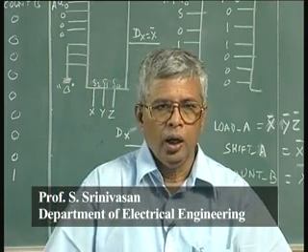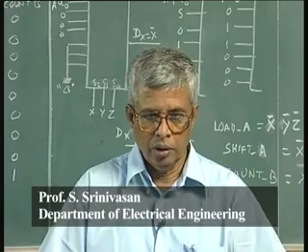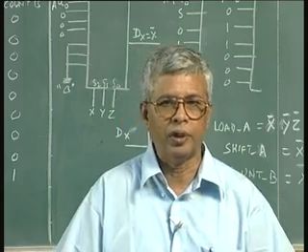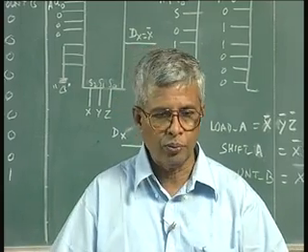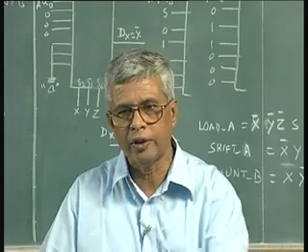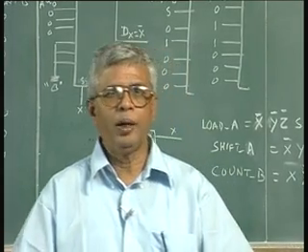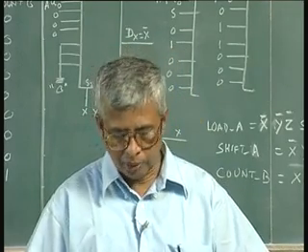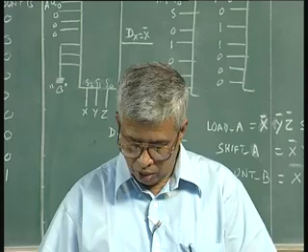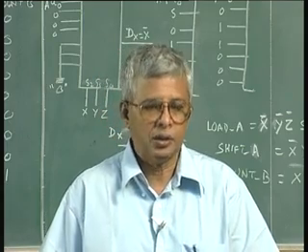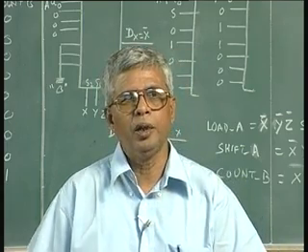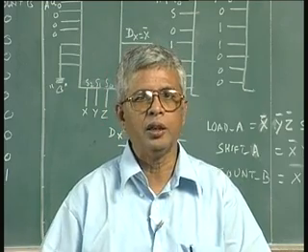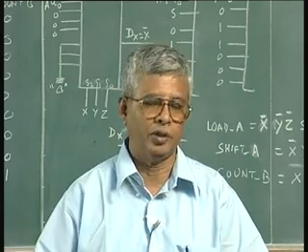And then we talked about how, instead of going through gate solutions or simple building block solutions, we can go to higher levels of integration. We talked about integrated circuit evolution from small scale integrated circuits to medium scale, to large scale, to very large scale integrated circuits. So, we talked about SSI, MSI and LSI components for combinational and sequential logic. We talked about multiplexers, decoders, PROMs, programmable logic devices, programmable logic arrays, and programmable array logic, and also how to use these in digital design, either for combinational design or in the steering logic of sequential circuits.